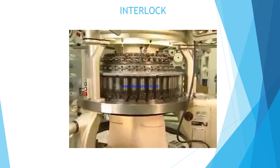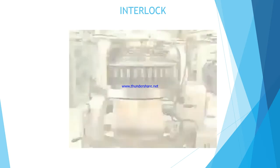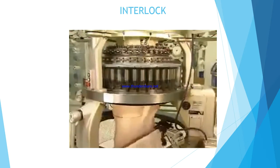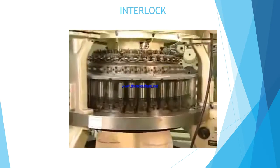Different double knit constructions can be made on rib and interlock gated machines. Needle selection by mechanical and/or electronic systems, along with yarn selection, determines the design effect.